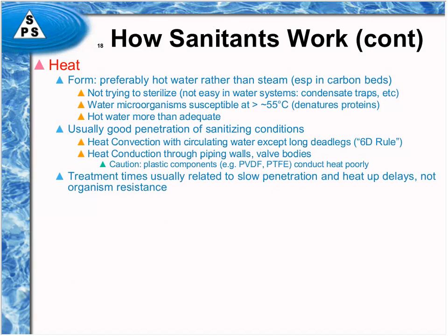Anyway, the treatment times associated with hot water are typically a function of the heat-up delays and not a function of organism resistance. You may have treatment times of an hour or 2 hours or whatever with the hot water, and it's not because it takes an hour or 2 hours to kill the organisms, because they die as soon as they get above 55 or 60 degrees. They don't last but seconds. What usually is the reason for the long treatments is that it takes that long to heat up some of the places in the system that need to get hot. So that's why the long treatments.